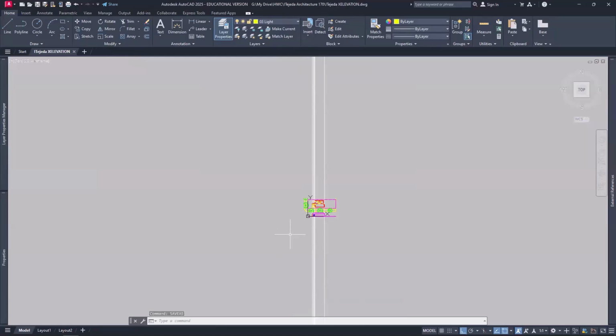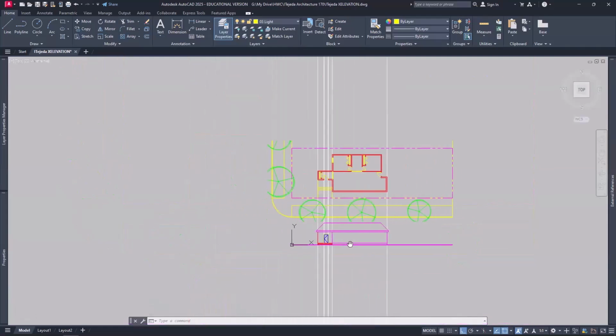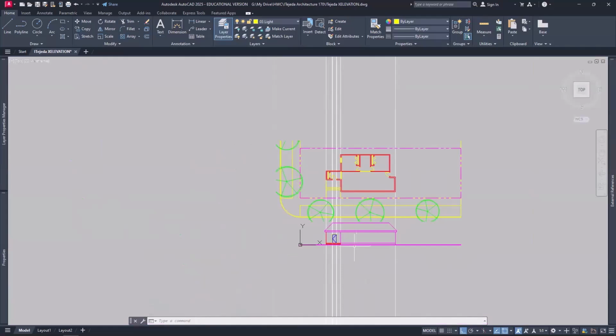All right. So what I was saying, the X lines will extend infinitely, but when I zoom extents, Z enter, E enter, it does not take them into consideration or into account. So that's a really nice feature. Okay, I'm checking time and I want to wrap this up and I can continue later, but if you have this elevation done and you want to start the next one, here's what you do.